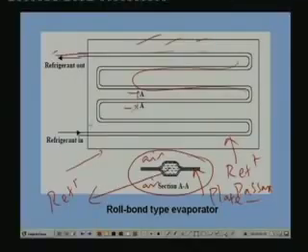So what you have is a single plate, which is made of two separate plates, a single plate consisting of inbuilt refrigerant passages through which refrigerant can flow. So that is what is shown here. Finally, when everything is over, at this point the inlet and outlet tubes are welded to the roll bond type evaporator. Through this tube refrigerant enters and from this it comes out,